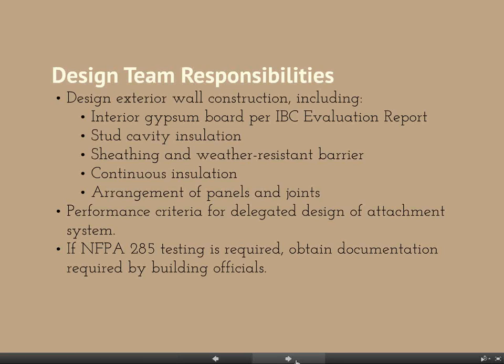So you're talking about 24 or 30 inch wide panels, and if you're having to do something that's less than that or some oddball module size, you're going to probably pay significantly more for it than standard. Yeah, it depends upon how many, because you don't cut them in the field. You have to, because they have those special shiplap long edge joints. They have to be fabricated at the factory.